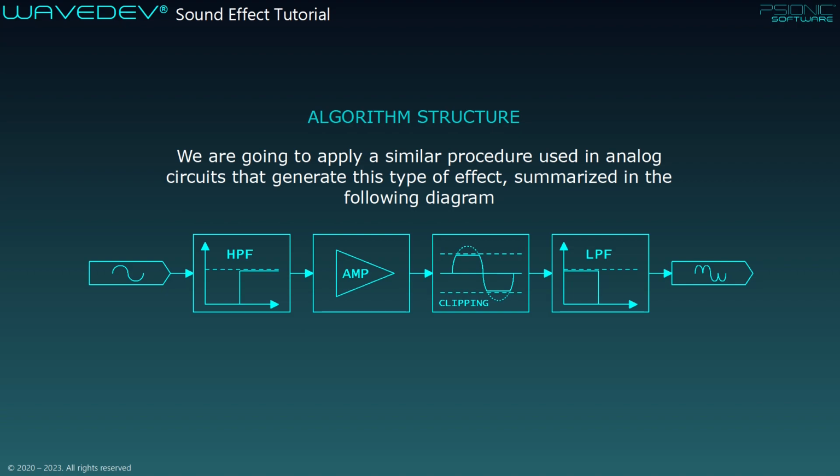The last stage is undoubtedly where you will have to invest more time in research. This block corresponds to the output filtering or post-saturation stage. At this point, we already have a spread spectrum signal. So we are enabled to apply multiple filtering layers, then simulate the additional equipment that accompanies a distortion: the amplifier, the cabinet, and the microphone, plus the environment condition, like the room.